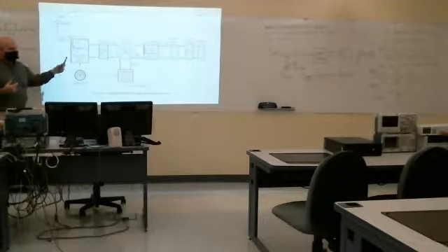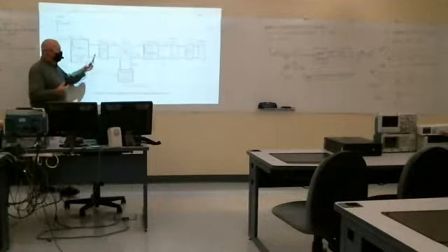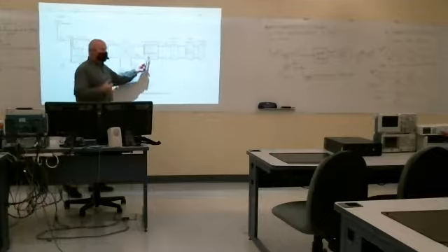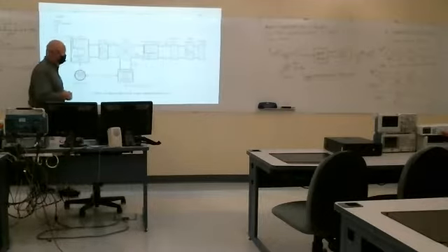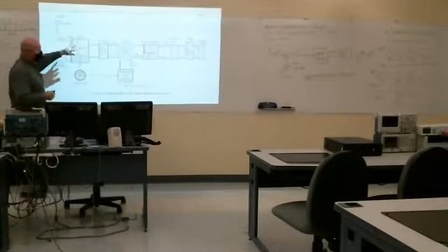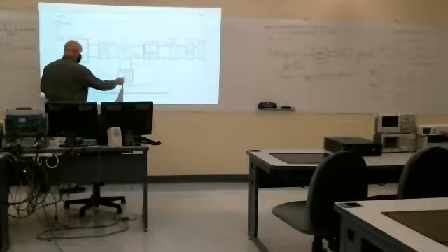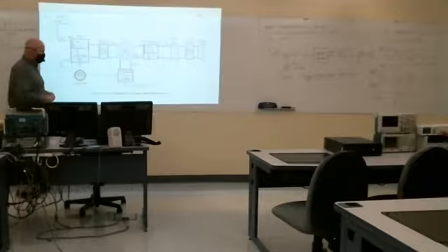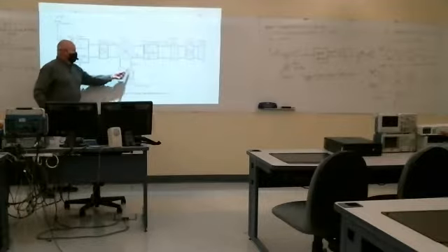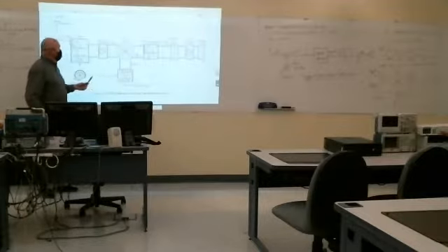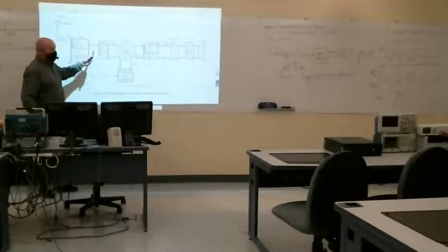Because you get the sum and differences, you can actually get two different channels that appear at the intermediate frequency. So this is present. I ignored it. The channel selection is actually done by when you turn the tuning knob, you're adjusting the frequency of this local oscillator. They also show a radio frequency amplifier that I didn't show in my diagram.